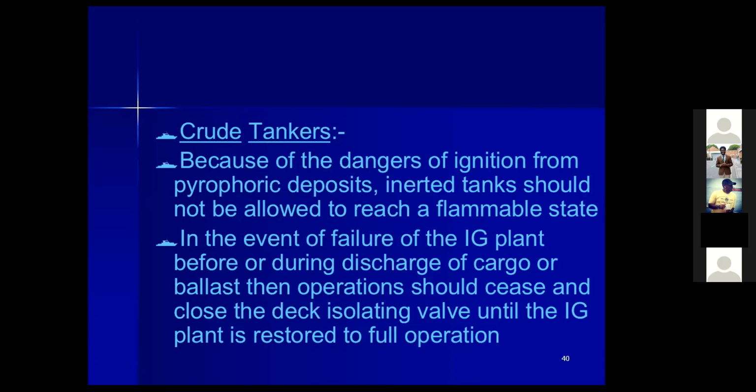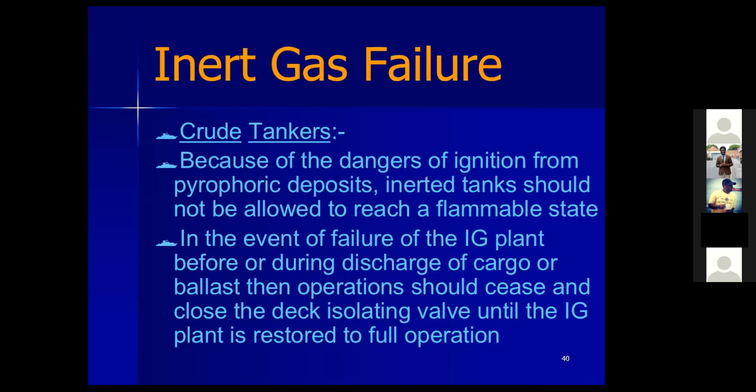So the inert gas plant must be checked and ensure it's working perfectly. In short, if it means that a technician comes to check, it is very, very important, because the quality of inert gas you send to the tanks says a lot. Rather than trying to prevent explosion, you might be exposing the ship to explosion. So it's very, very important.